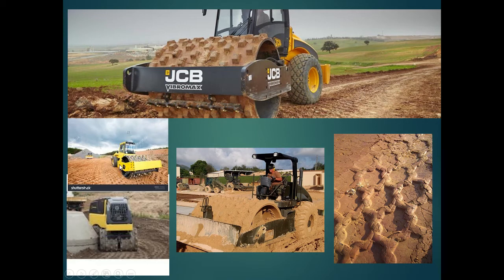Okay, so again, here's a manhole. See how tight this can get? And I mentioned this over and over: it's very important that we get compaction tight, close up against the sides of the manholes, so we don't get any piping of soils, sediment, and so on into manholes.